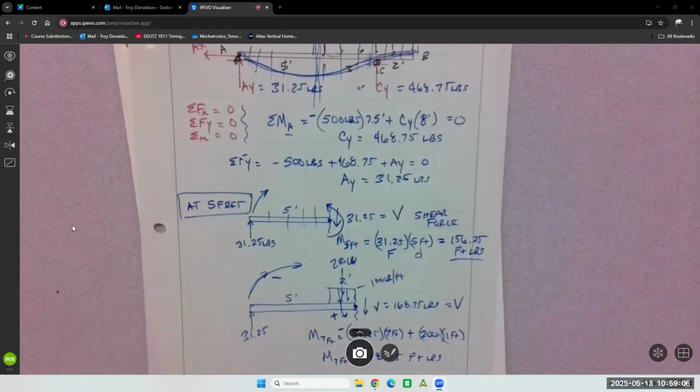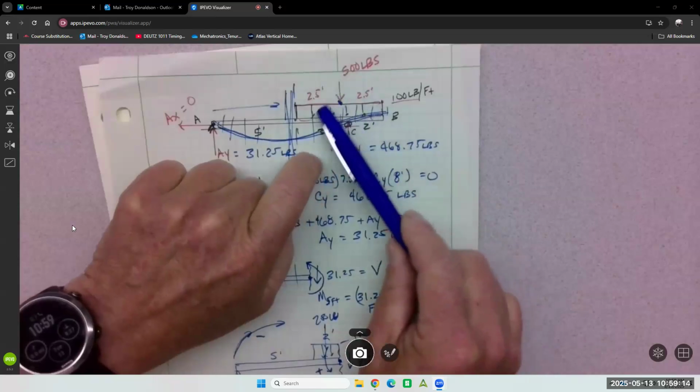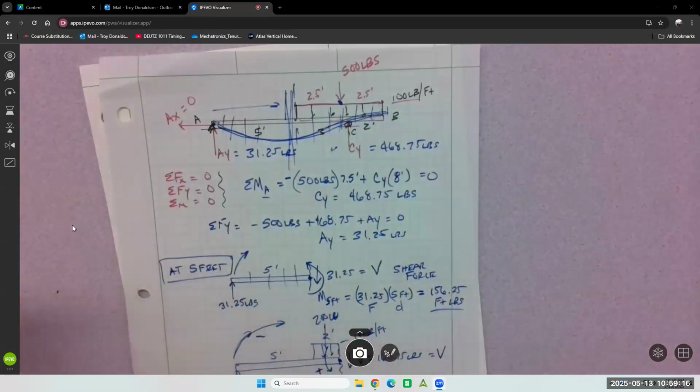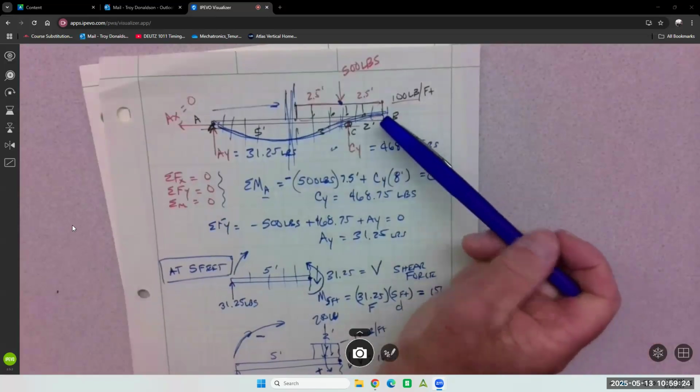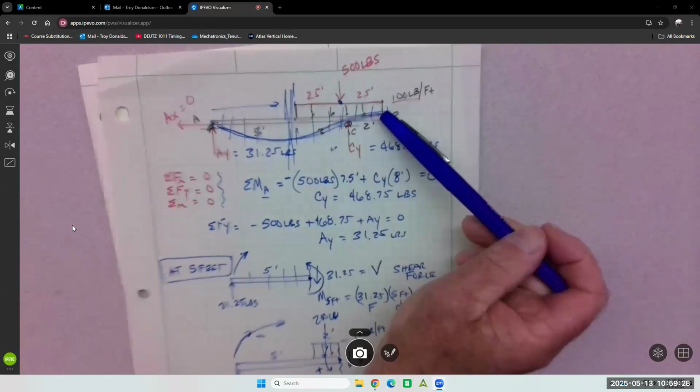And it's not necessarily underneath the big loads, not always, right? Because we happen to have a support kind of under this big load that's helping hold it. It's tricky. I bet this bending moment's gonna go back up out here, because this is kind of cantilevered out, right?